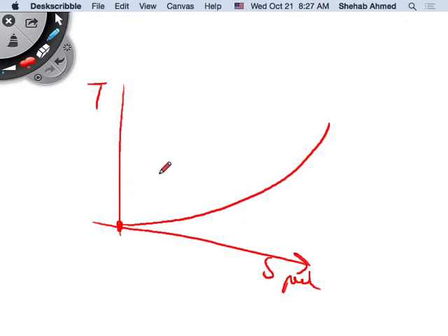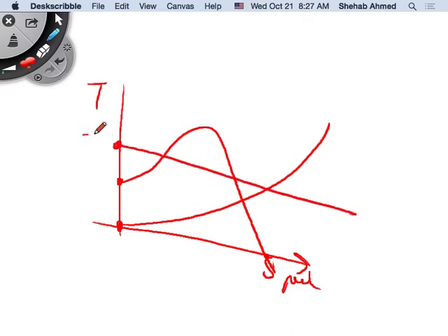So in this application, a motor that has low starting torque will be okay, right? But in an application where you have a lift that requires a certain minimum torque to start the lifting process, this motor's torque speed curve will not work. You have to have a motor's torque speed curve that is above this point, right? If this is the torque speed curve of the motor, these are two different motors, or the same motor started two different ways, for example, right?